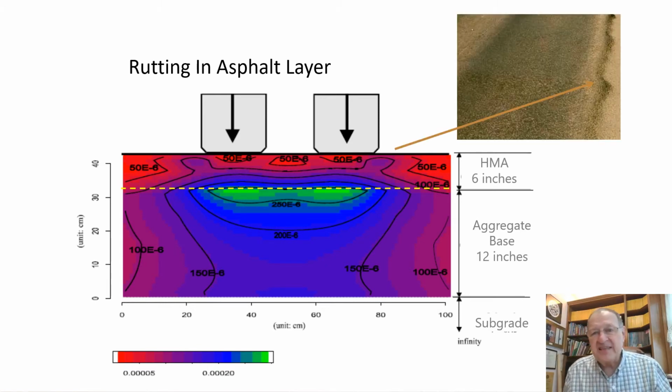And it's exactly that shear stress that is causing the rutting to happen and to have that hump along the edge of the wheel path. Now, the key thing here is that it's a sign that the aggregate skeleton in this mixture is too weak to carry the shear forces that are being imposed upon it by the trucks.